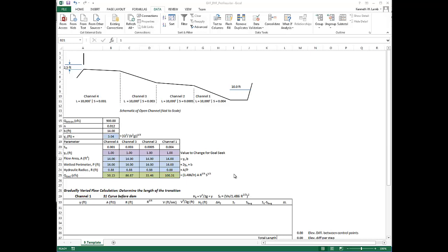In our case, we would like Excel to run the goal-seek command for all channel sections. Chances are you're not familiar with Visual Basic and cannot write your own code yourself. Excel has the ability to record the commands that you will run through its main interface. Once you see the recorded commands, it is easier to enter the VB code window and simply edit the code as needed rather than write the code from scratch.